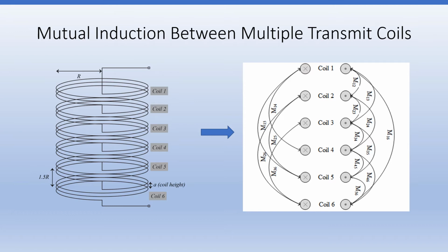We began with the calculation of the mutual inductance between multiple transmit pairs by finite element method over Maxwell's relation. The results were verified against experimental results. Triple Helmholtz coil pairs were coaxially arranged to provide a uniform coverage inside a 10.6 liter acrylic cylinder, where the coil geometry and spacing had been optimized in our previous study. Despite having similar geometry, each coil will have a different inductance because of mutual inductance with nearby coils.